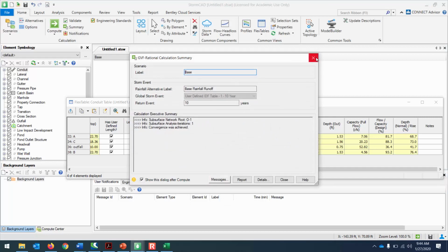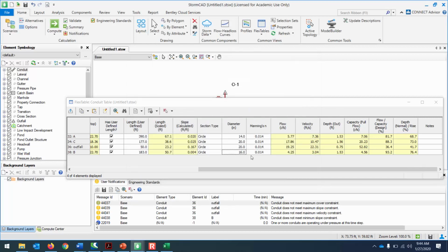Yeah. All right, so we know that this is the optimal design because if we make any of these pipes smaller, then they're going to be over capacity. What other optimization could we do? Well, if you were actually designing this network, you could choose different depths for the inlet boxes. The standard assumption is maybe you'd put your inlet 5 feet underground.